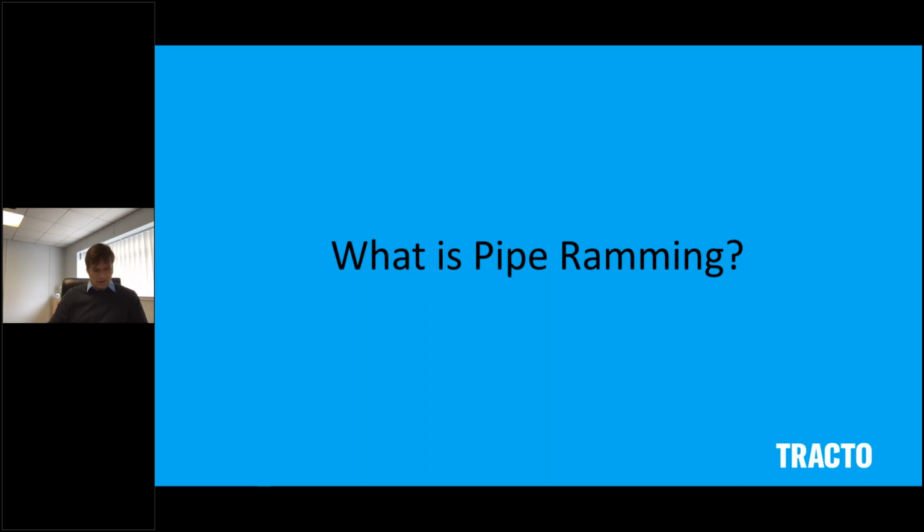cable installations. The pipe is generally open for the installation, and the front soil cutting shoe reinforces the front edge of the pipe and directs the soil into the pipe during the ramming process. Spoil removal from the pipe is usually carried out after the entire steel pipe has been installed and is in place, and it is generally achieved by either augering, compressed air and water, or, with bigger pipe diameters, with conventional earth-moving machinery such as mini diggers or skid steer loaders.